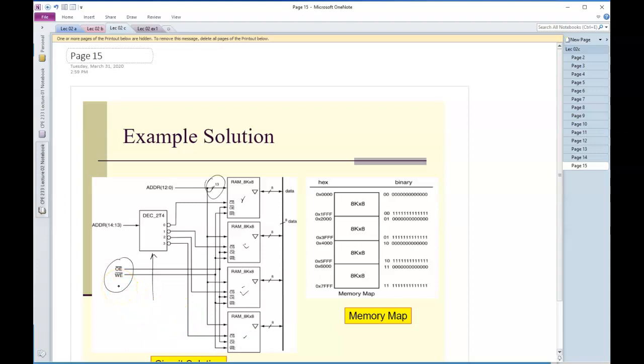That means the control signals for this 2 to 4 decoder effectively become the 2 most significant address bits. In this case, it's 13 and 14, which are essentially bits 14 and 15 in the word here. You can see it over here once again. There are 4 sets of bunches of 1s and bunches of 0s. These are equivalent, the difference being this row right here, which is assigned by the decoder output right there. Looks good. And that's how I'm going to make larger memories from smaller ones.